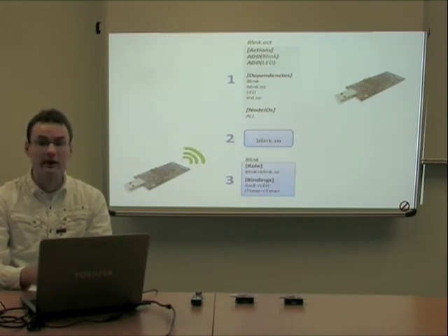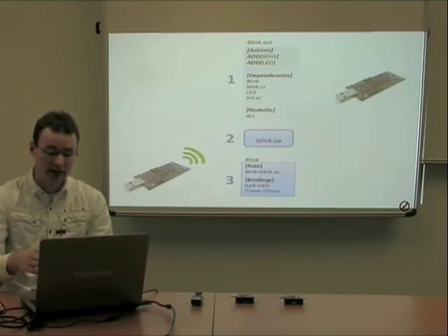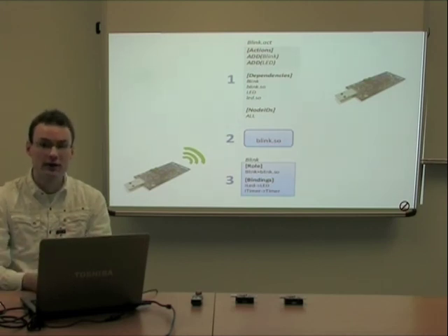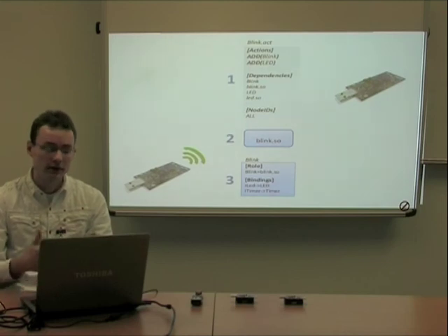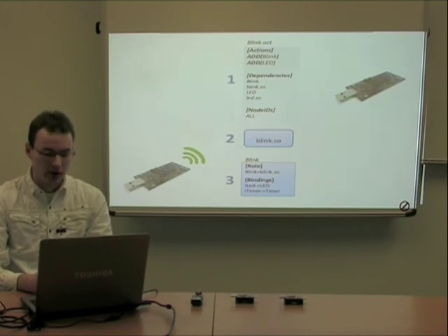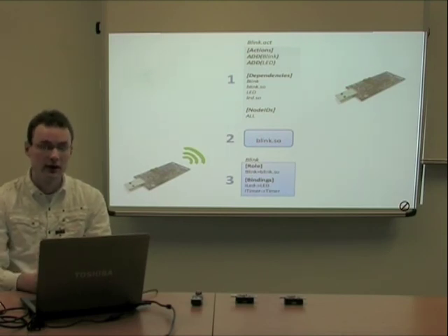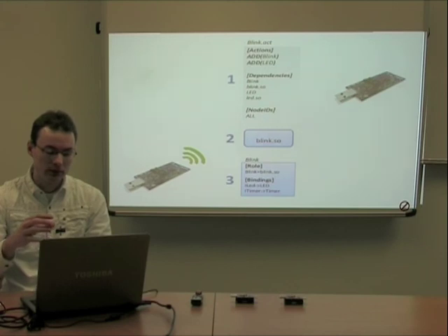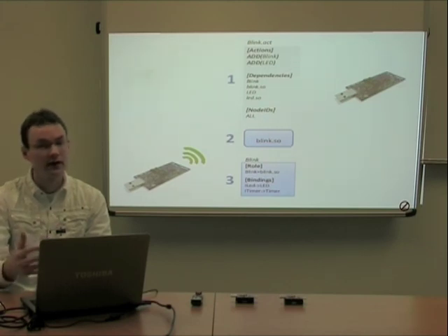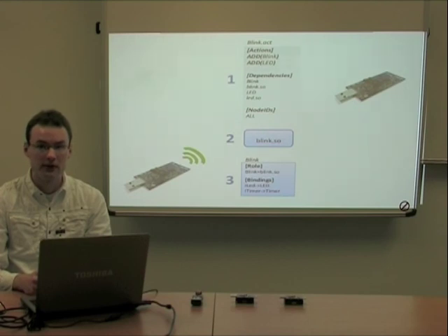And the third kind of file we have is a configuration fragment, which you see at the bottom of the screen here. And this specifies how any component fits into the broader architecture of the system. And this is a lot of how we get the very strong update independence of Lorien. So what you see here is firstly a configuration fragment only specifies the local dependencies of the component. And secondly, the dependencies are specified on abstract role names in the system. So LED and timer. Not specific components, just abstract names.